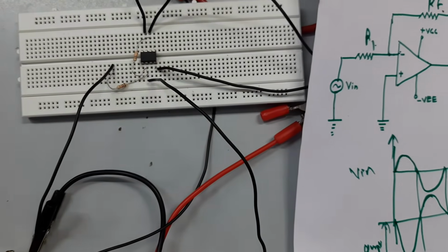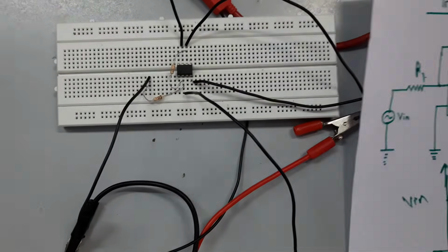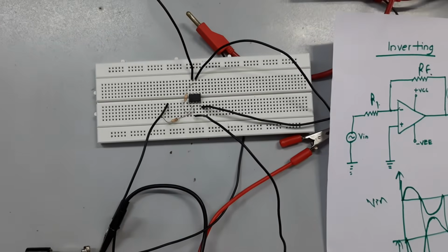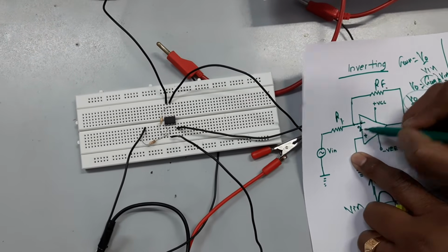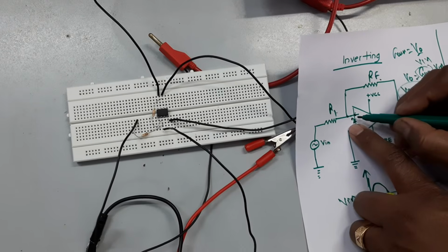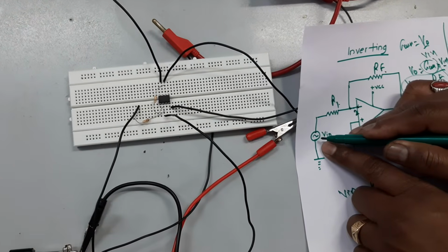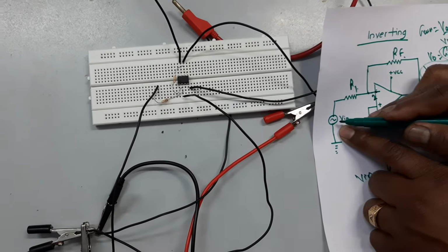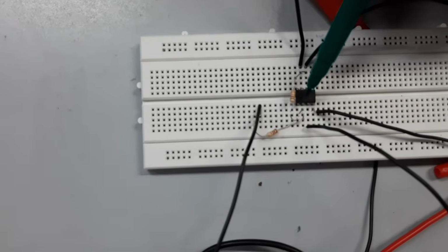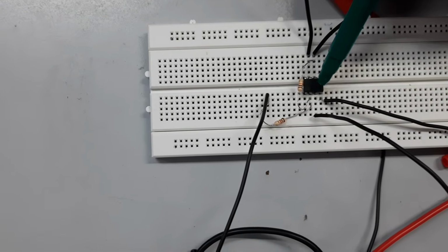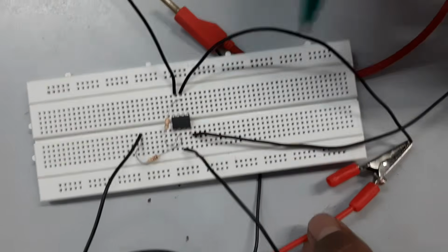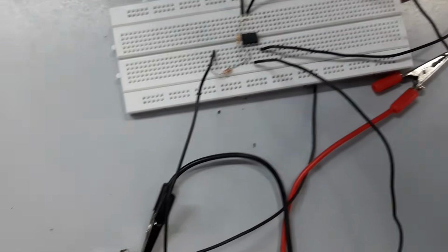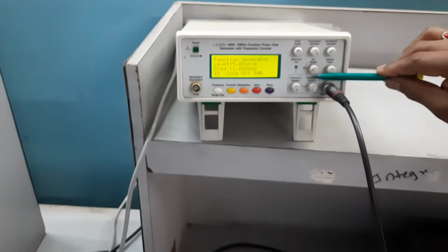So for example, if you see, this is my pin configuration, isn't it? If you want to trace this, it is pin number 2. Pin number 2 is my inverting input, right? So here I have connected a resistance, and to the resistance I have connected a sine waveform, means the function generator. So you can trace this here. From here you count, this is pin number 1 and this is pin number 2. So at pin number 2, I have connected a resistor, and through this resistor a wire is coming, and this wire is connected to a function generator, okay, like this.